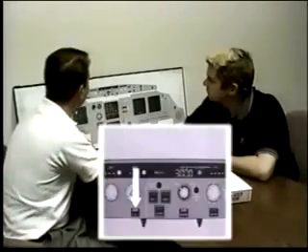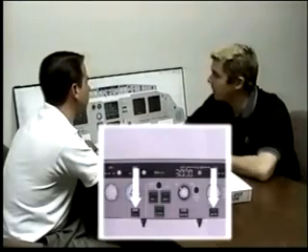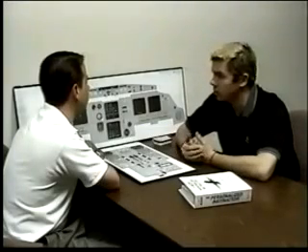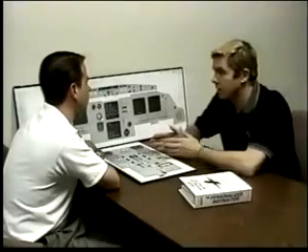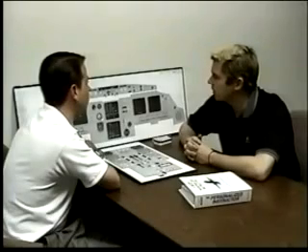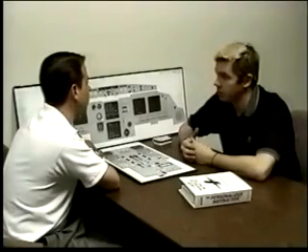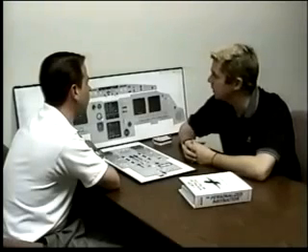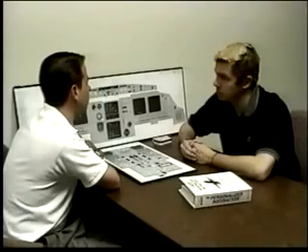Describe the difference between the LOC and the approach push button. Okay, the LOC is only used on an ILS system where the localizer is capable, and that's going to track the localizer course down. The approach button is used for an ILS system or for a non-precision approach for VOR, NDB in our database at United. The approach will, during an ILS, arm both the localizer and the glide slope.